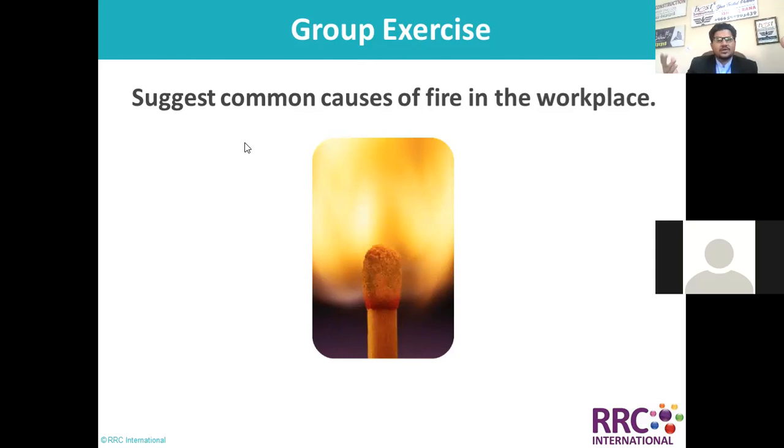I mean, we are sleeping at home and a fire broke out and it's all burned at our workplace. What happened? In one incident, a person just dropped his key. He was a maintenance technician, and the pipe had a pyrophoric iron sulfide layer. That means a combustible layer, kind of like combustible dust. The key fell down because it was in the front pocket, and the moment it fell on that pipe, it created a small ignition and it was all over, because the area already had extremely flammable fumes, and it was a refinery.